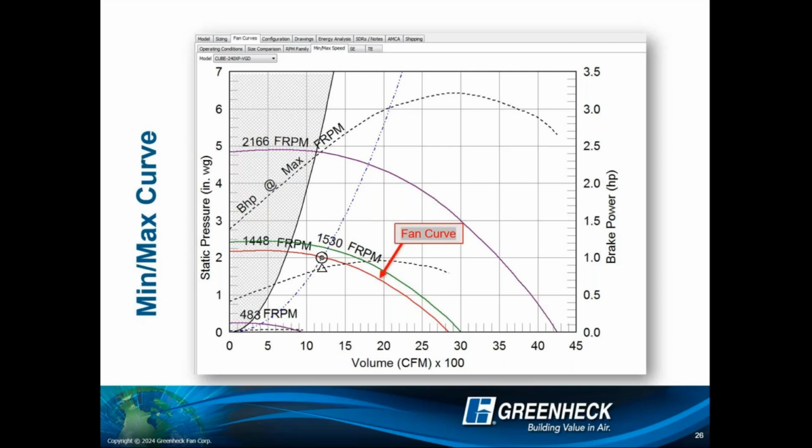data requires, when Greenheck tests these and creates these fan curves, they're using 3 duct diameters in and 3 duct diameters out. I do think we're going to get this later in the presentation, but these all represent ideal inlet and outlet conditions, and a lot of the times in your field you're not going to end up with that necessarily. I've seen a lot of elbow work before that will actually affect where that operating point ends up.